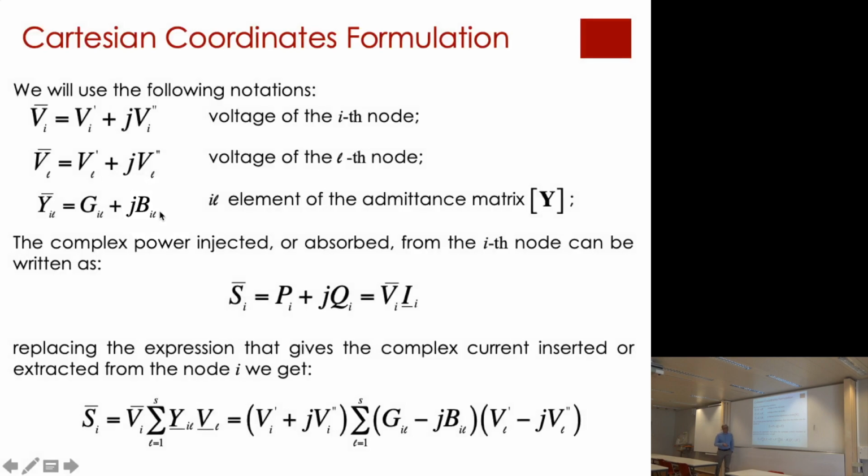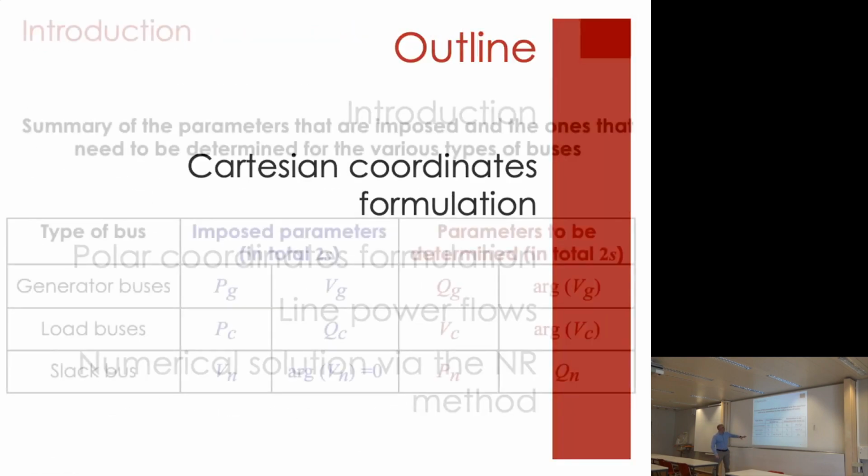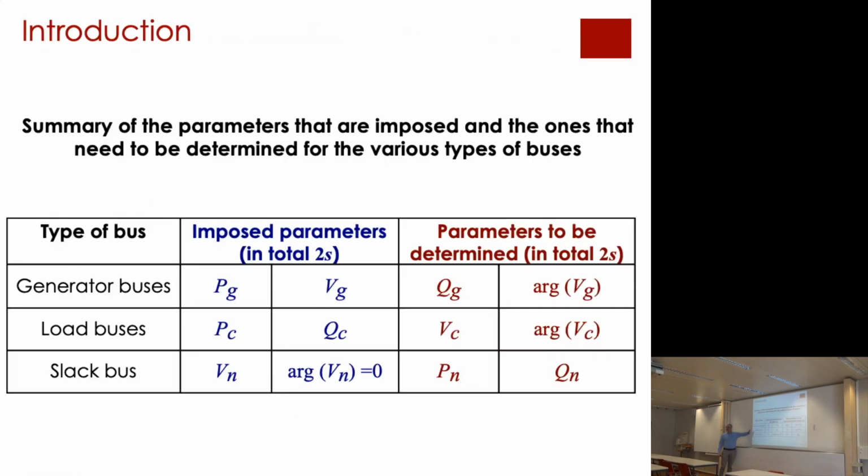Okay? Now, I don't know whether you paid attention, but here in the load flow problem formulation, we get rid of the currents. So essentially in the load flow problem, we are writing everything in terms of powers and voltages. Okay? Why that? I repeat again. Powers, because they're essentially according to the operational aspect of the market and the dispatching.